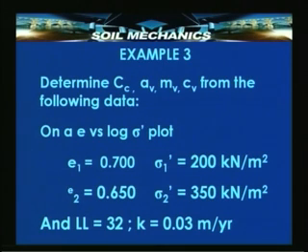Now, let us see an example. To begin with, let us see how to determine the various soil parameters from a typical test. I shall not be going into the details of the data from a test. Let us assume that we have the data. Given the data of dial gauge readings versus the time, we will be in a position to have the basic data required for computing the void ratio, as per one of the methods which I described just now.